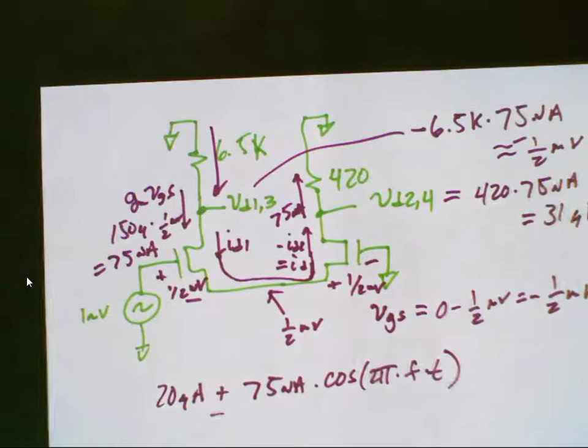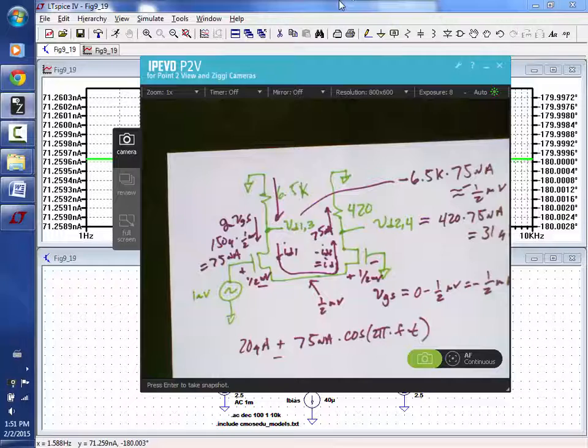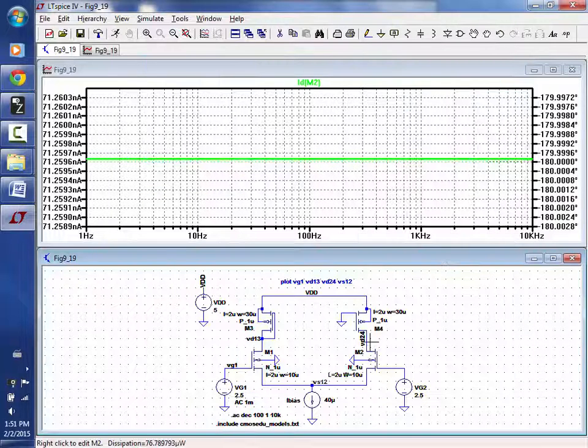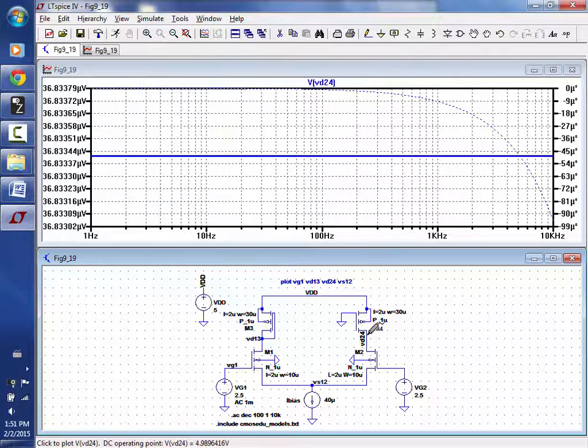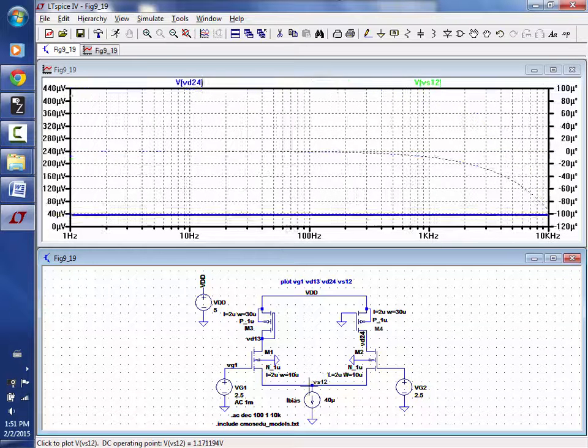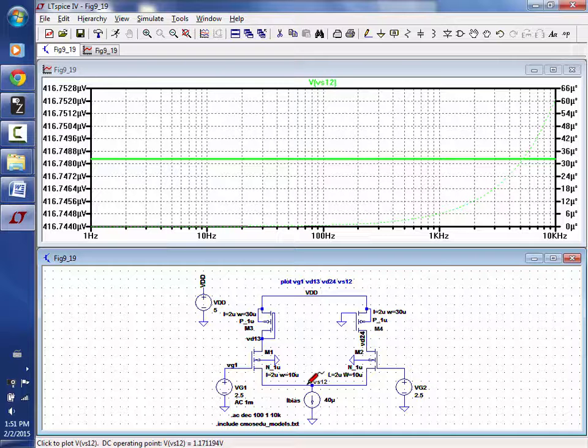All right, let's look at a couple more, then let's look at the time domain, then let's move on. Okay, current over here. Oh, we just did that. Voltage here, we calculated 31 microamps. Here it gives us 36. What other signals? Oh, we looked here. This was half. We calculate half a millivolt. We got 416. Am I missing anything? Okay, this is just showing magnitude, correct? Let's go show the overall currents and voltages, both AC plus DC, because AC sweep only shows the AC.